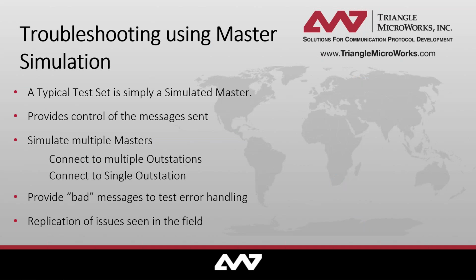So now that that question segment is over, let's get back to a few more examples. When testing an outstation, you might want to use a test set. A typical test set is simply a simulated master. A DNP3 master simulator allows for sending messages and controls to the outstation from a single master or even from multiple masters. This will allow you to test your outstation in various situations without requiring the actual hardware.